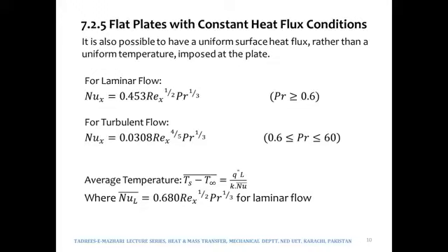If we consider the wall at the same temperature, means if we consider an isothermal wall, then the temperature of the surface would remain the same throughout. However, the heat flux would then be different. And if we consider the constant heat flux condition, then the temperature at various locations would be different.